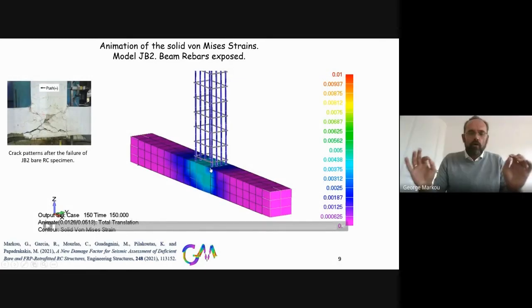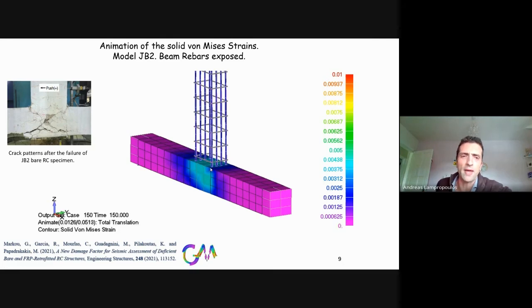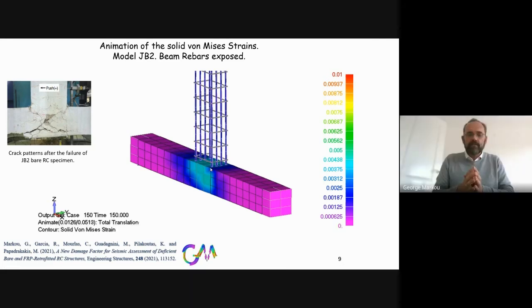Okay, you take practically at the bottom where is the largest effect. Exactly. So you say how many opening and closing of cracks do I have in that finite element, in that hexahedra? And what embedded rebars are found in that region, and then you go and change the internal forces transmission from the embedded rebar to the hexahedral element, and therefore you take into consideration the effect of the damage of the concrete, because at the end of the day, if the concrete is damaged, then you will have slippage, right?